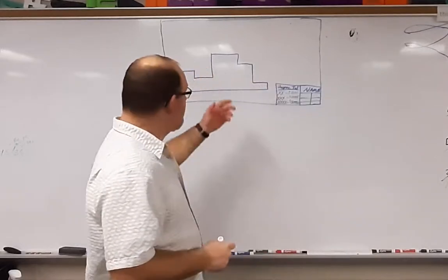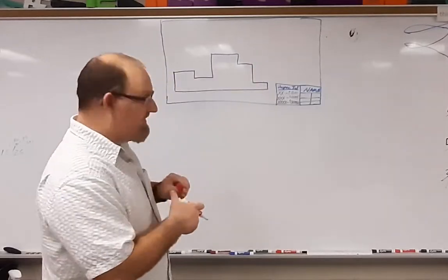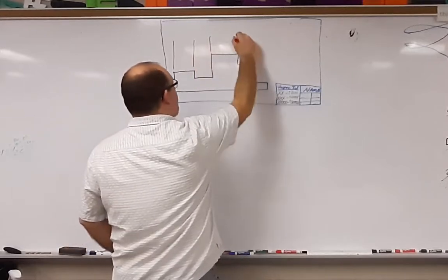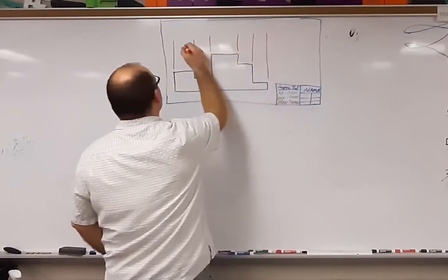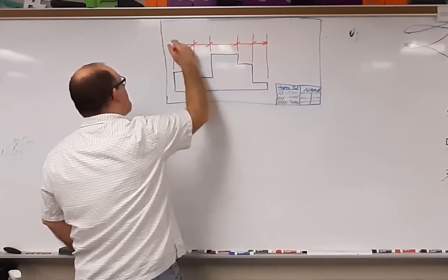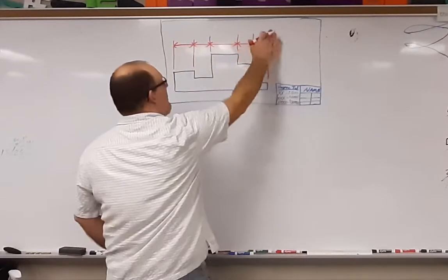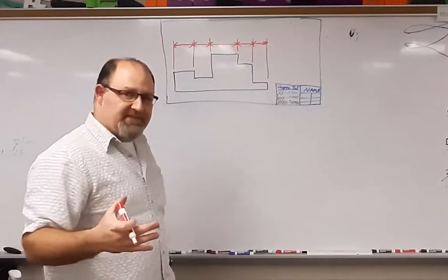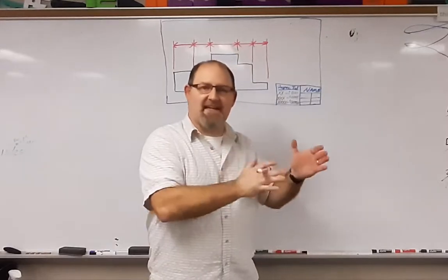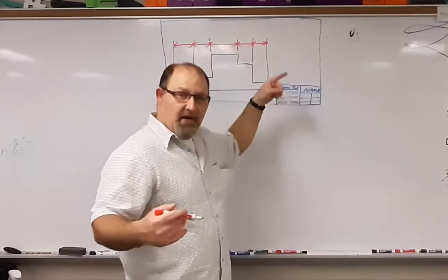So we have a part, let's say it's a steel plate, and this steel plate has 5 different steps, if you will. So let's say that we have dimensions on this. Something like that, okay? So this first method we're going to be looking at is called chain dimensioning. It's called chain dimensioning because it simply is linking one dimension off the next, off the next, off the next. So let's go ahead and throw some numbers up here.